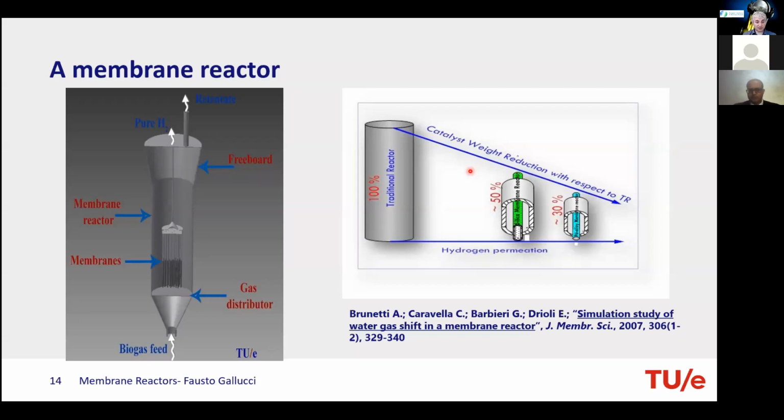So you see that you have to have the two working together. So you lose a little bit the degree of freedom in optimizing catalyst, optimizing separation because they have to work together. So to use a membrane reactor, you have to have some challenge in the reaction you want to carry out such that the membrane reactor can help you.